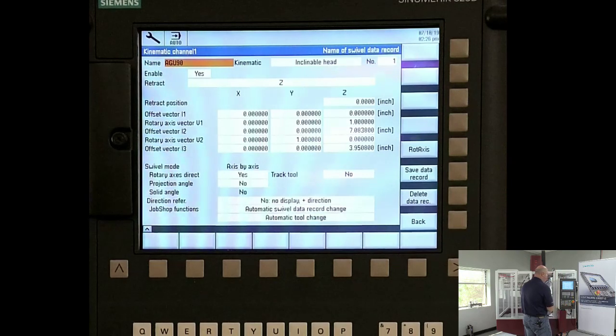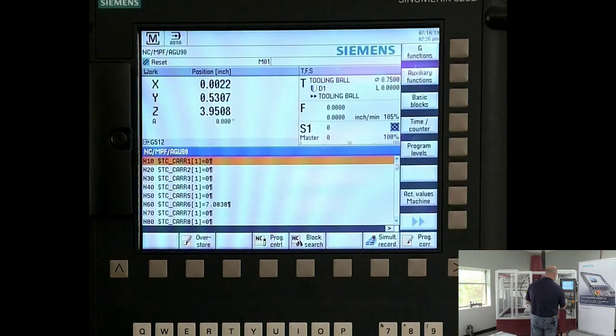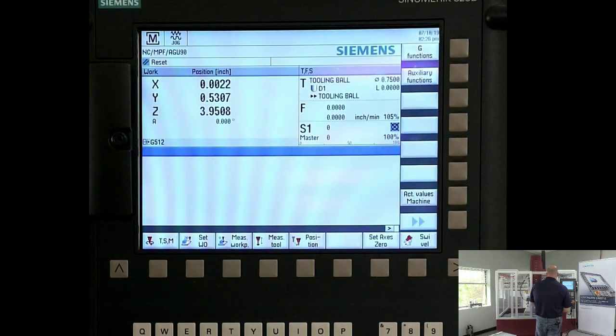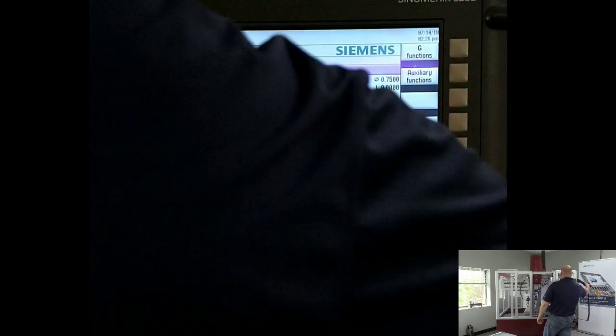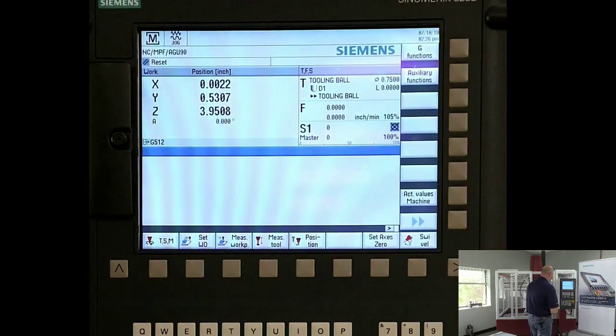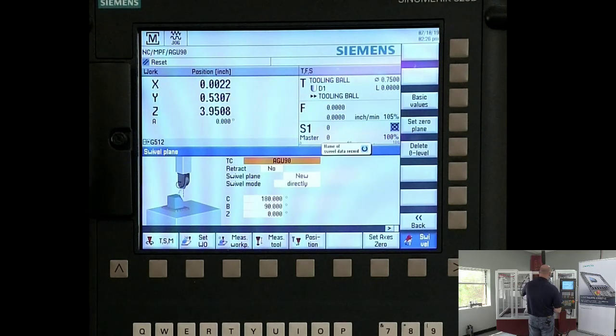So how do I check the rotation of any axis? And this can work on a full 5-axis setup. But what I do is I use a tooling ball. So what we're going to do right now is we're going to set up an offset. But first things first, I want to set a 0 up at the point I'm at right now. But I need this 0 to take into account now the kinematics of this machine, my 2 joint offsets, right? My 7.8 and my 3 point whatever it was.